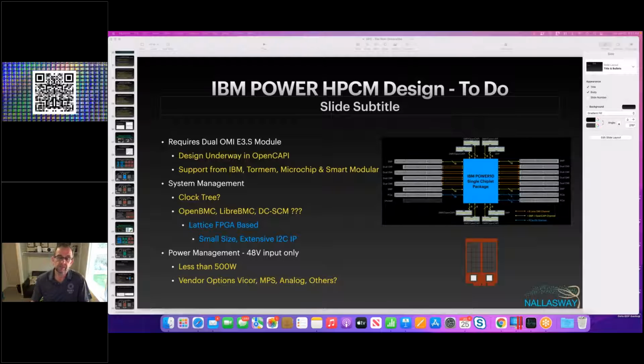So 2.0 is saying we're going to put LTPI on it and have all these parallel interfaces, and you can kind of do what you want. I would like to see 3.0 go to the bare minimum you need for these parallel pins, get this connector size down, and do everything over the LTPI. And there are actually 3 of those in the standard. There's LTPI 1, 2, and 3, which have specified different bandwidth and latency requirements.